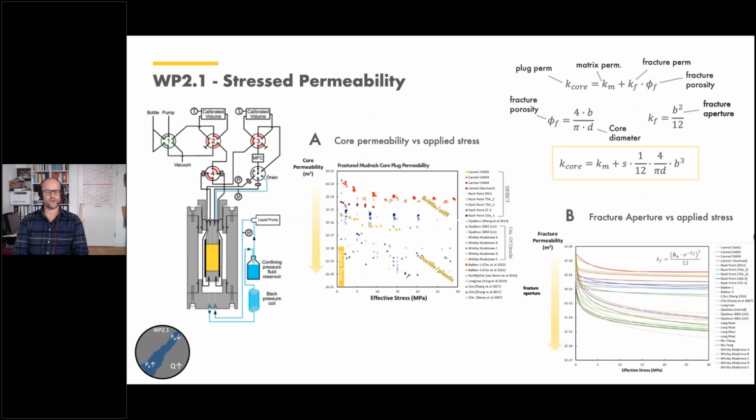So for that, we did a lot of laboratory testing of fracture flow under different stress conditions. So we put the sample under subsurface stress and changed the pore pressure. Basically, with an increase in pore pressure, we increased the permeability. And you see from the picture in the middle that permeabilities can vary by 7 to 8 orders of magnitude, which is quite a lot. But if we look at the mineralogy and the mechanical properties of these rocks, we find that the high permeability ones are usually the ones that are very brittle.